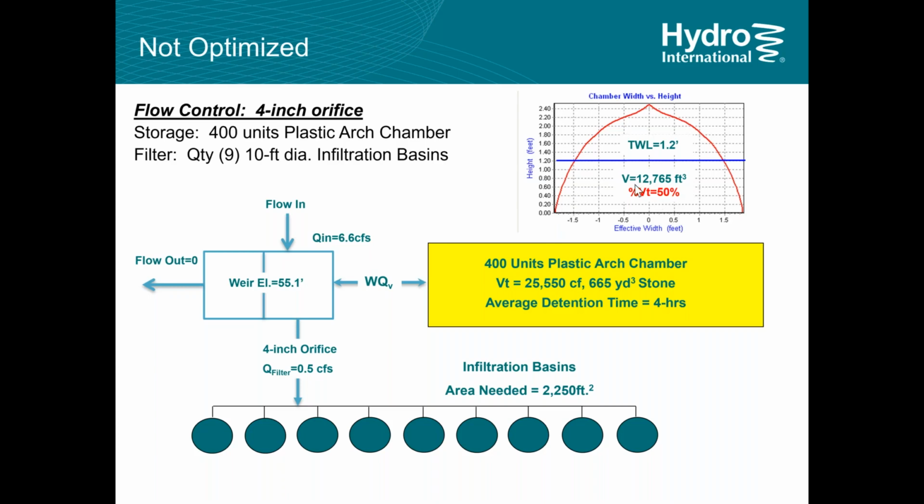But if you notice, that upstream storage, even though the whole unit is installed, it's only being half used. And this is due to the nature of the storm hydrograph. But you're really not making full use of that upstream storage.